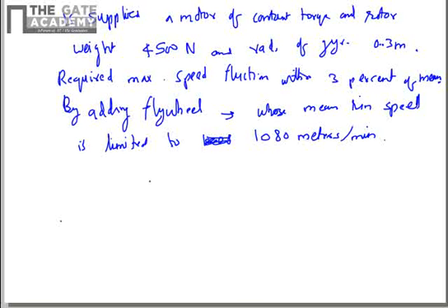This requirement comes from the side of the stress in the flywheel rim, the hoop stress. We know that it limits the maximum velocity because stress is rho v square. Rho is constant for a material, and v square is what limits the circumferential stress. So we know the stress limit of the flywheel that is dictated by the maximum rim velocity. So the problem asked is to find the weight of the flywheel rim.